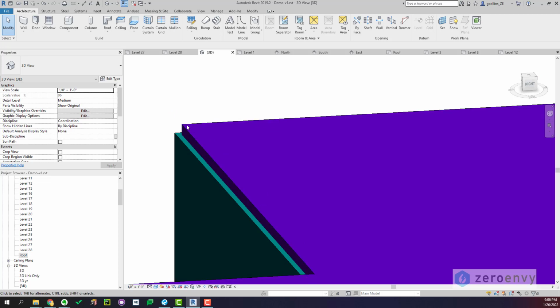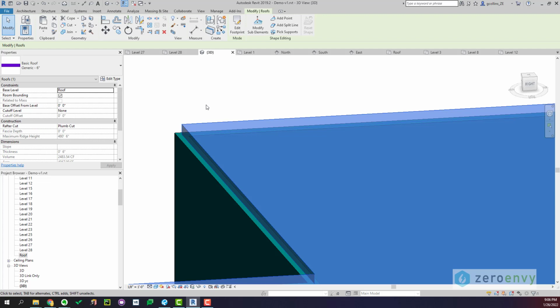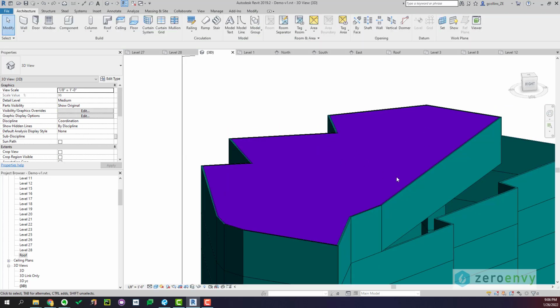If we don't do the 6 inches offset, you can see how the top surface will be floating, and so there will be a gap, and this top surface is going to become a shading element in the modeling software, and that's something we wanted to avoid. So for roof, we have always been applying a 6 inches offset, so that will fix that issue.